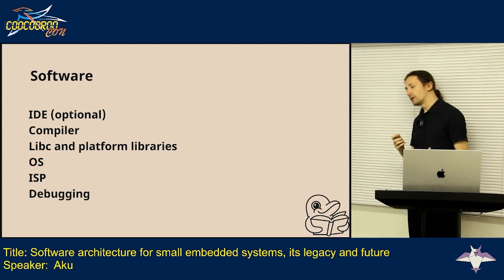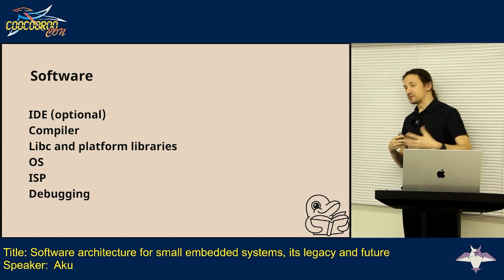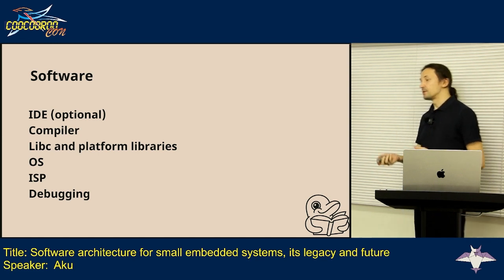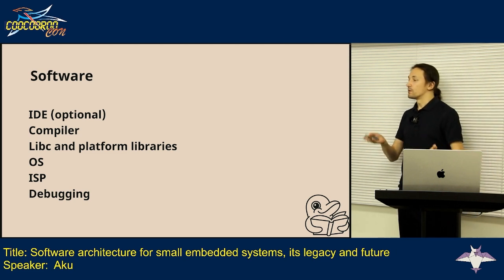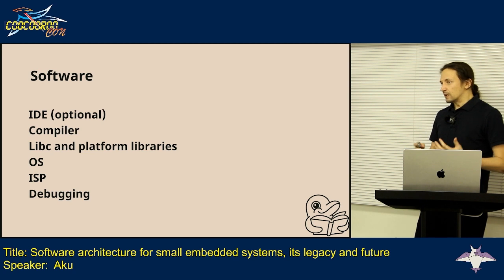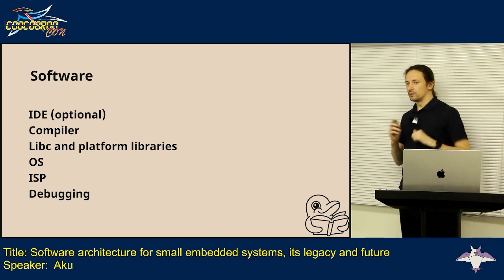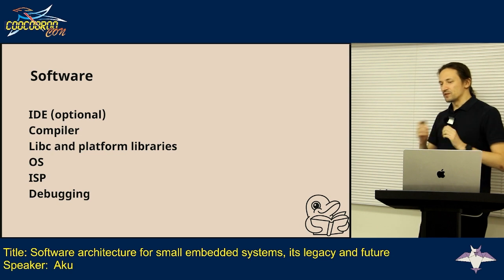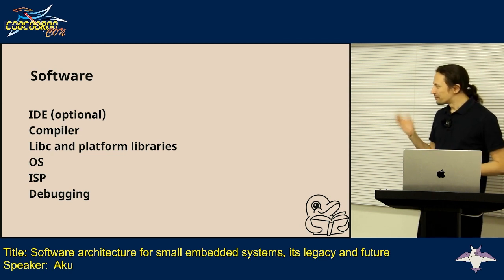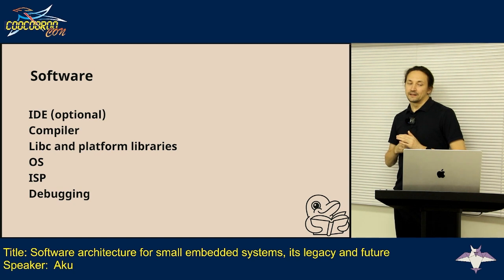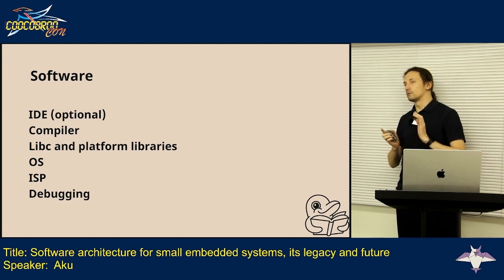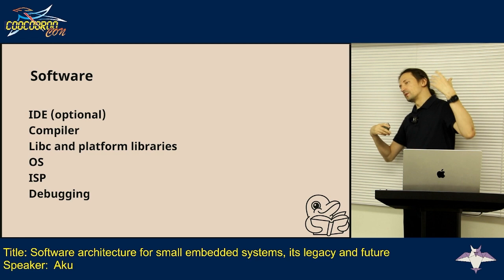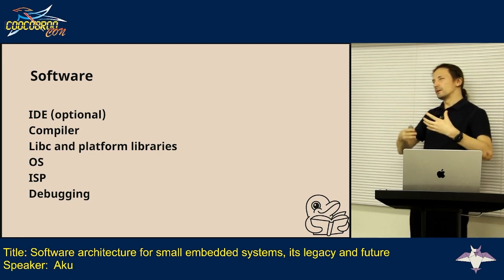And then when we have a compiler, we need some standard libraries. The standard libraries that we use for our traditional applications on, let's say, Linux, macOS, or Windows are a little bit too thick to be used on such small devices. Another problem with them is that they usually expect reentrancy to be synchronized with your kernel, and reentrancy is handled in a way that is very expensive.